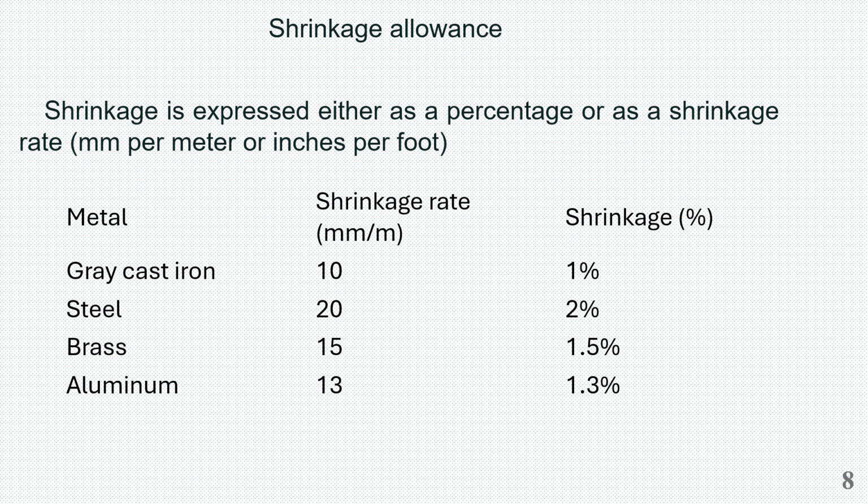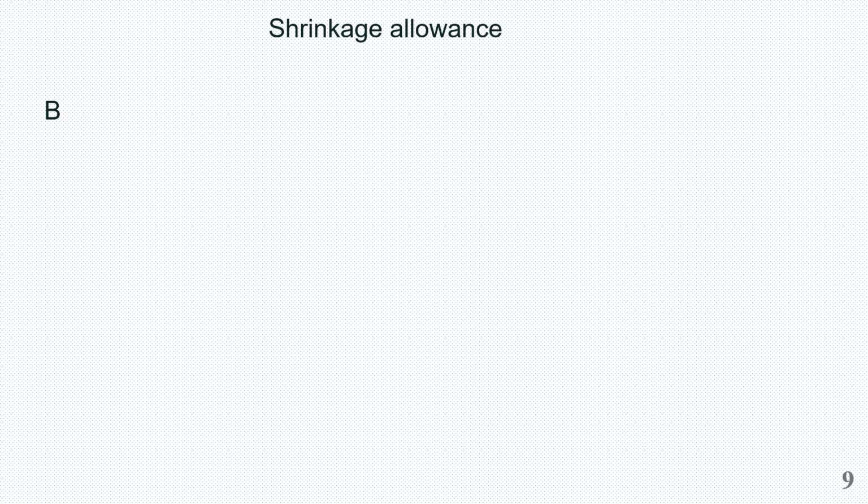Remember, these are just a few materials. Each and every material has its own shrinkage allowance and shrinkage rate. Correspondingly, you can consider those values while determining the final dimensions of the pattern.